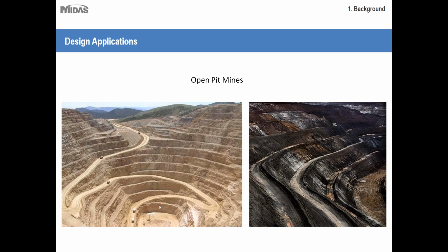Open pit mines are dug on benches, which describe the vertical levels of the hole. These benches that you see here are usually on 4 to 60 meter intervals depending on the size of the machinery being used. But many quarries do not use benches as they are usually shallow. Anyway, most walls of the pit are generally dug at an angle less than vertical to prevent and minimize damage from falling rocks. This depends on how weathered the rocks are and the type of rock, and also how many structural weaknesses occur within the rock, such as faults, shears, joints, or foliations.